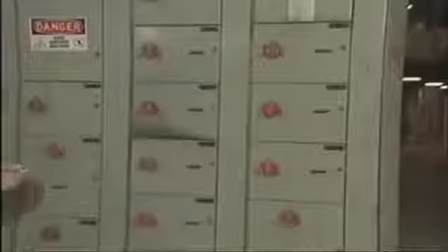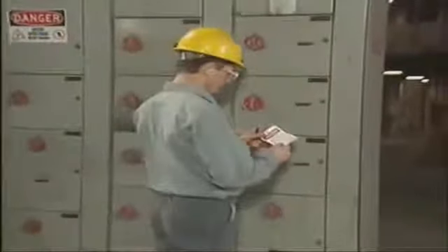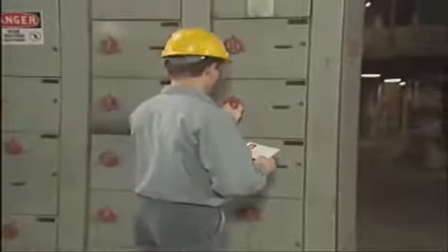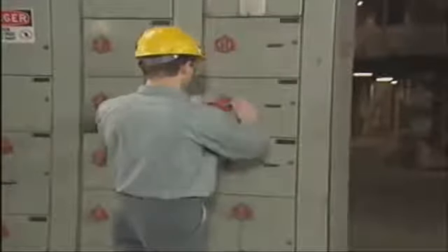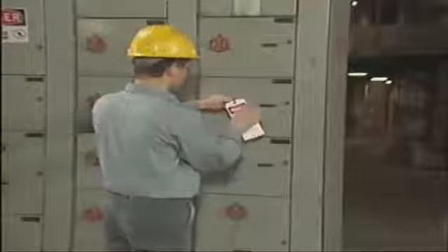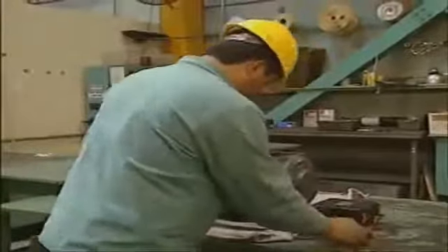In this part, we'll look at general procedures for troubleshooting a DC motor, and we'll see how to test for grounds, opens, and shorts. The motor to be checked should be de-energized, locked out, and tagged according to approved procedures. Troubleshooting a de-energized motor helps prevent personal injury and protects the motor and the test equipment from damage. The motor in this example has been taken to a shop for troubleshooting.